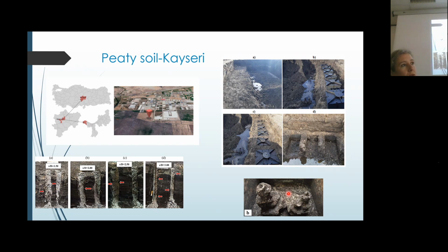Because of the distribution of the fibers, whether horizontal or vertical, the behavior of the soil really differs. Anisotropy is totally complex here. Even with the preparation of the stone columns or jet grouting, we are dealing with many problems in getting the exact or proper column. So we are working on that issue.